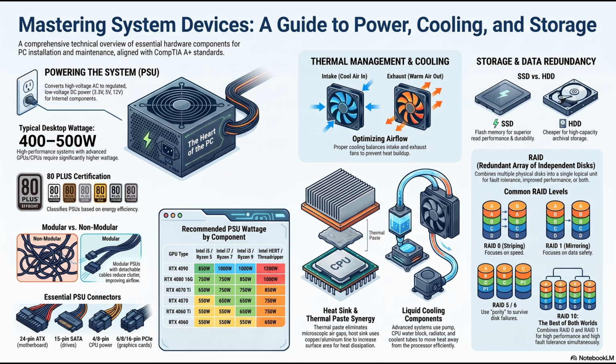Right, the disaster. A dropped server could mean millions of dollars in lost high-frequency trades, or the failure of a life support monitoring system. Uptime must be guaranteed. So how does a redundant setup guarantee that? Is it just a really tough, oversized power supply? It's actually multiple, entirely separate power supply modules housed within a single server chassis connecting to a unified backplane.